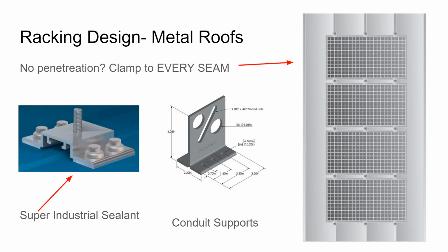And so the advice from the standing seam manufacturers is to clip to every single standing seam to get the best load distribution across the standing seam roof.